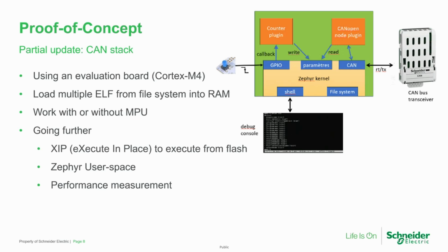It means if you want to use user space in LLEXT, you have to take care of this kind of stuff. You have to give some authorization like you do on a mutex or semaphore on Zephyr, to grant some access. I think it's not done yet in LLEXT, but we have to work on that. And we had to do some performance measurement to see if having code which is loaded has the same performance as code which is not loaded, because if we have a drawback, it can be very bad.